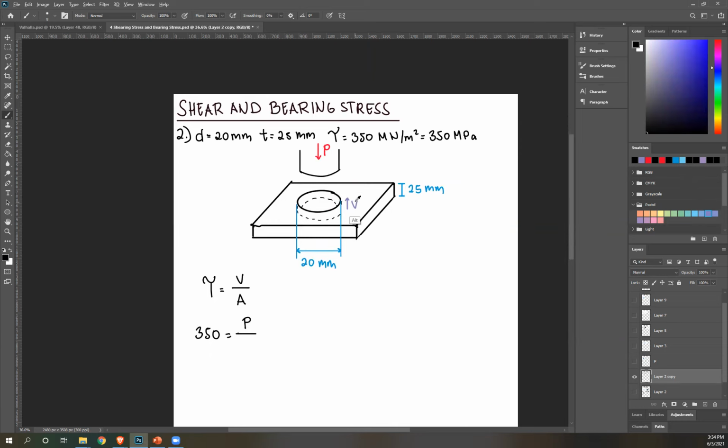So this is the area experiencing your shear force or your shear stress, right? Can anybody give me the equation for that area? In case you don't know, this area is just the perimeter of this circle multiplied by this thickness. Very good, Dragon. 2 pi r h.